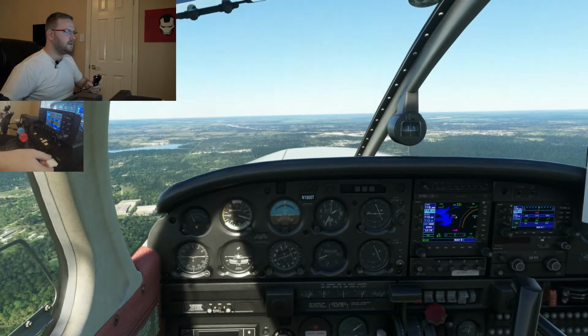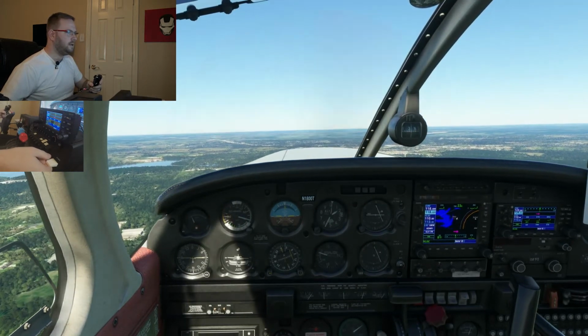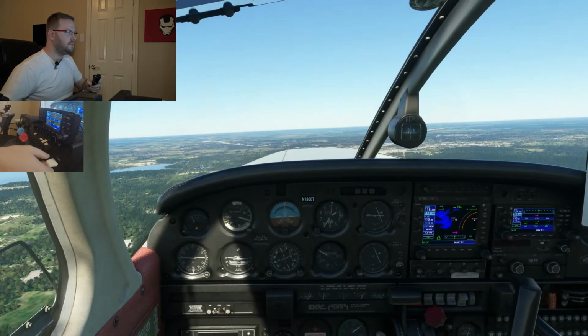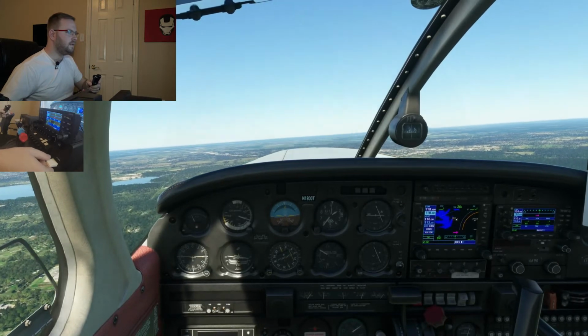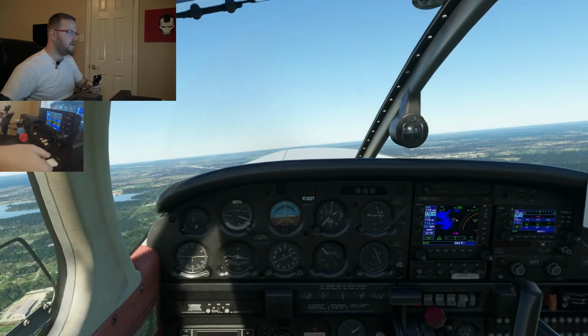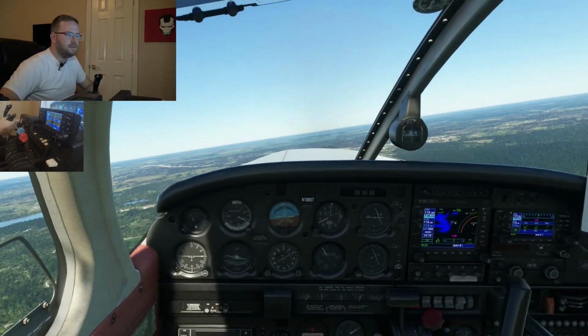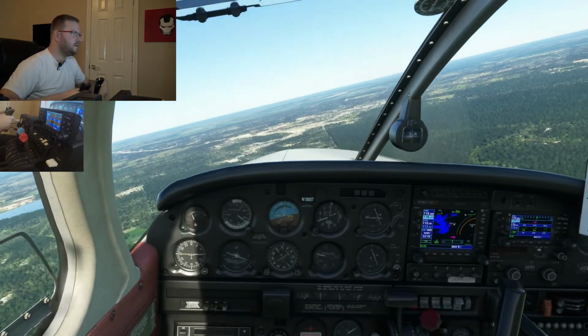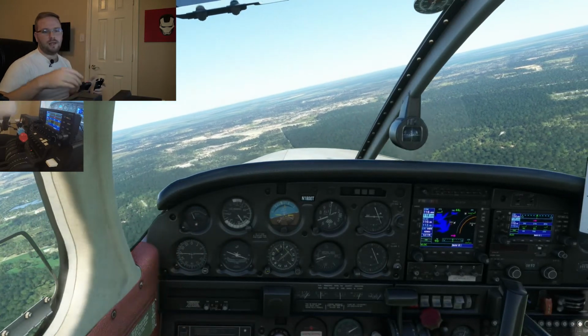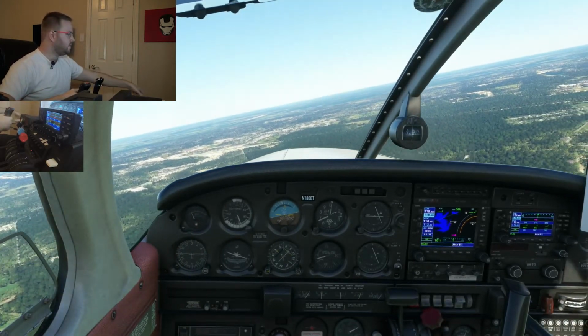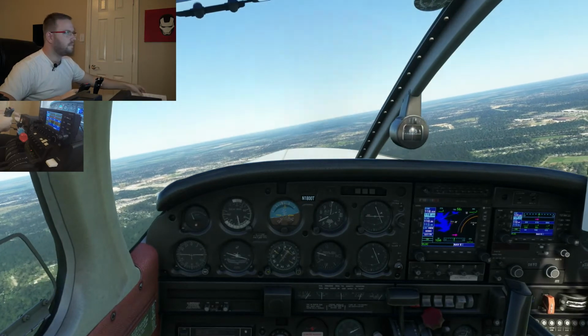Wait until we are no longer falling and climbing. Remove our second notch of flaps. And third notch of flaps. And that is the end of that maneuver. So we can go ahead and turn towards Conroe Airport. We can get the ATIS for our next step, which is diverting to an airport.